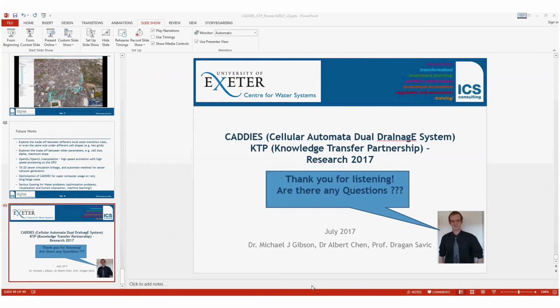May I know what equation is used for infiltration? Is that SCS? So you provide a hyetograph, so that's steps from one rate to another, but basically you're providing the rate per time. Yes. And then we just remove that water given how much time has passed.